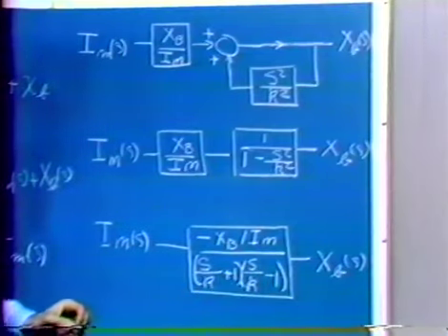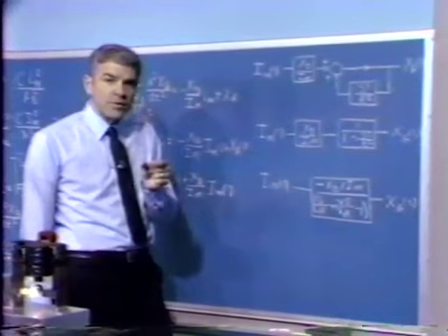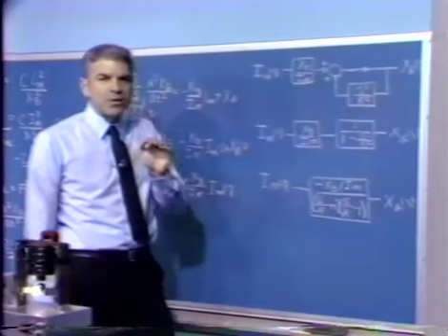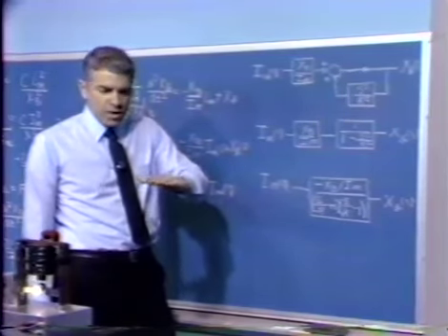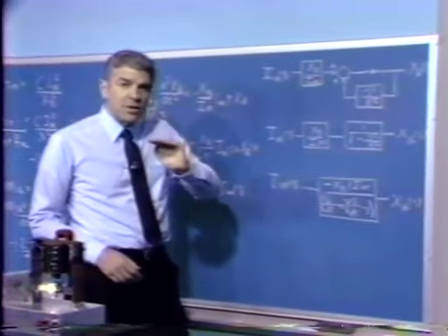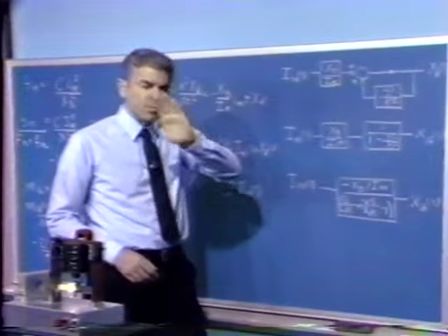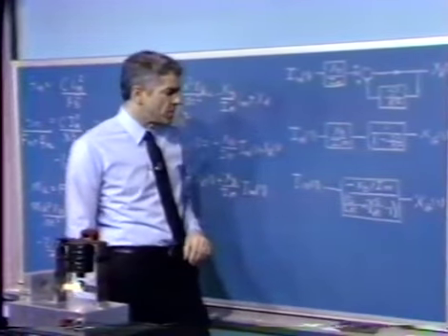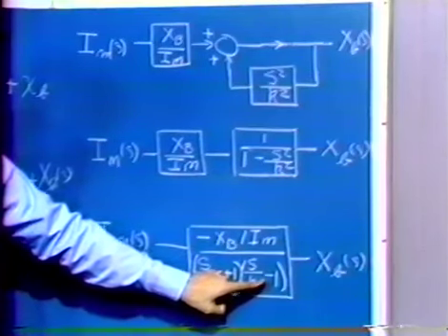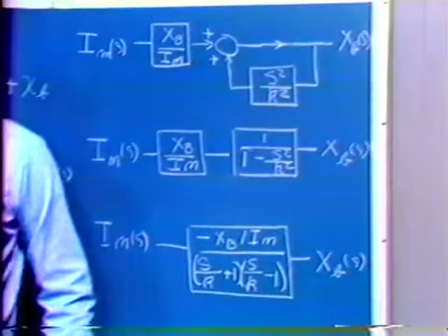In a linearized analysis, if we looked at the behavior of the ball for small displacements from equilibrium under the conditions of a fixed magnetic field, we'd find that as the ball fell away from the equilibrium point, either downward under the force of gravity or upward into the magnet, the deviation from the equilibrium position would be exponential for small displacements, an exponentially growing displacement from the null position. So that behavior is reflected by the pole in the right half plane in the transfer function that relates ball position to magnet current.